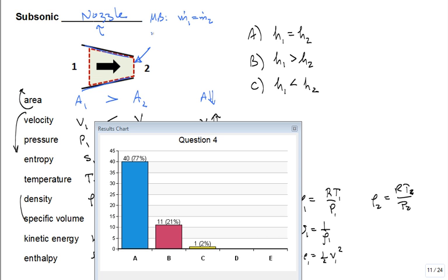For our energy balance, I know that we could have the most general form, transient, heat transfer, work transfer. No heat, no work, steady state, no changes in elevation. What does it boil down to? Enthalpy plus kinetic energy is?